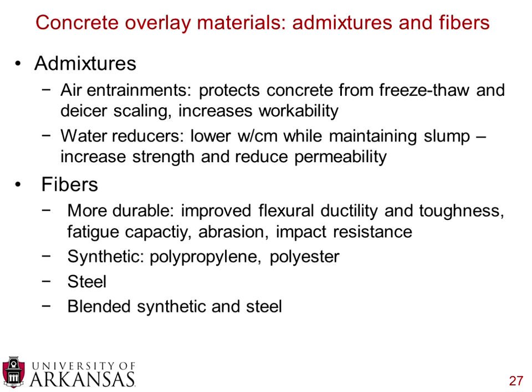This is basically like small plastic fibers, and you want to make sure those are dispersed nicely through the mix. Sometimes they clump. If you put these bags in, you'll have a big ball of fibers. You want to try and make sure that it gets mixed as well as possible. And then also some people have played with blending synthetic and steel fibers. So there's a lot of interesting literature and research out there about incorporating synthetic fibers.